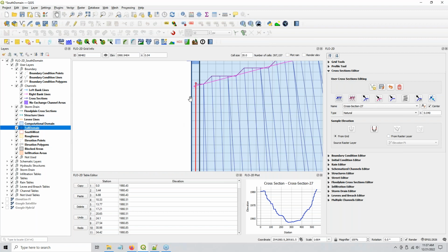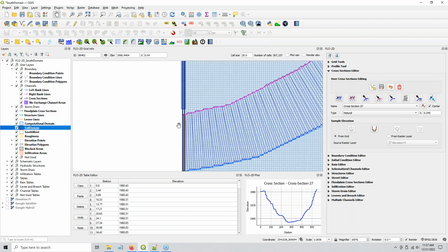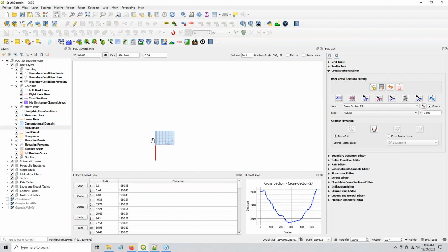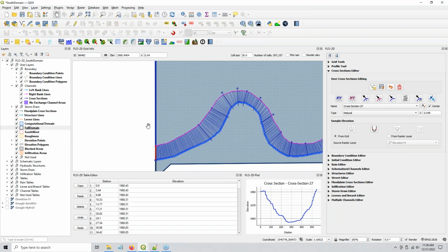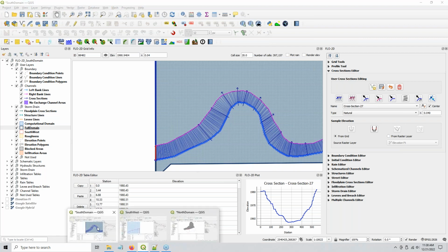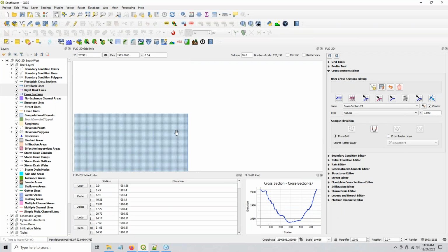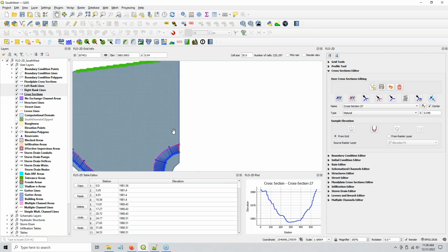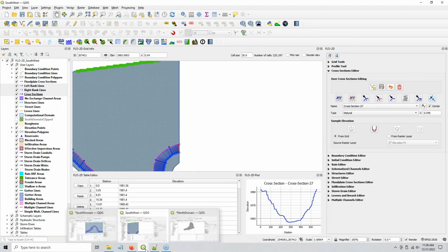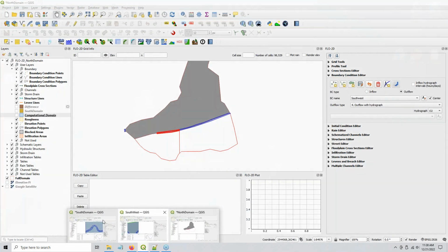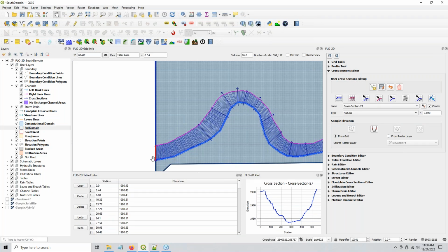Let me turn this image off real quick. This right here. And what happens is that these outflow nodes fill the southwest domain. Along here, they become inflow nodes for the southwest domain. And then for the channel, I take the hydrograph from the channel at the very last cross section, and I develop that into a hydrograph for the channel in the downstream model.